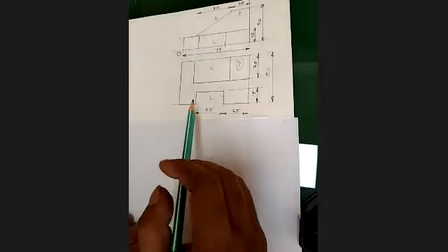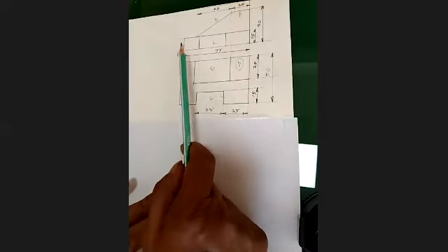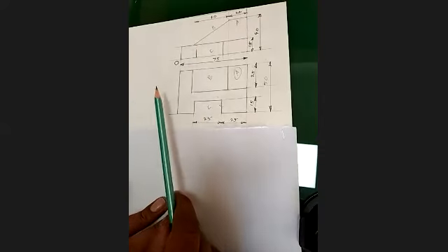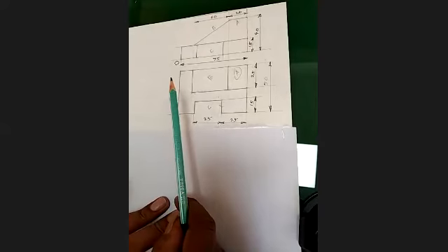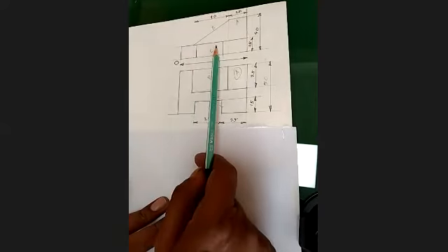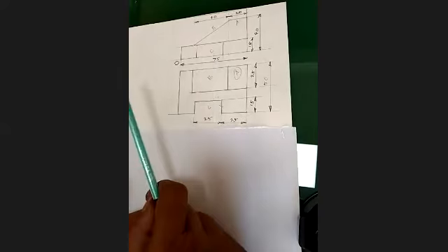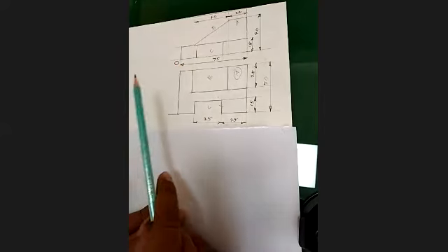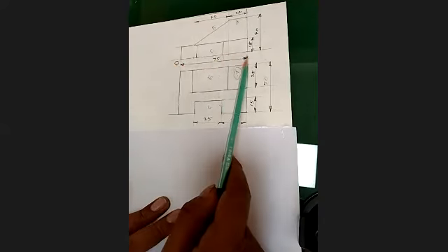So this is another typical problem on isometric projections. You just look at the views given here. As I mentioned, views will be given with the first angle projection method, so that out of these two views, you can easily understand this is going to be the front view and this one is the top view. Now, origin is given on the left side, so your whole length is going to be on the right axis.